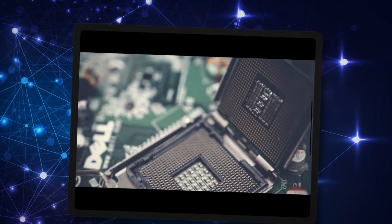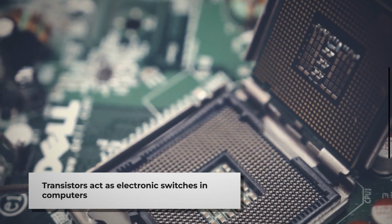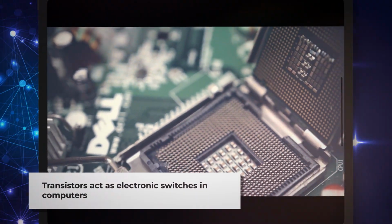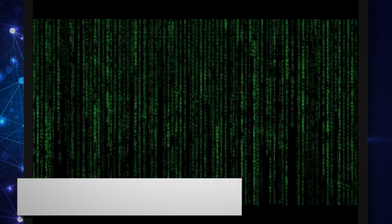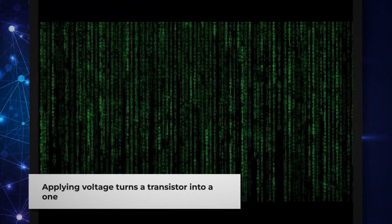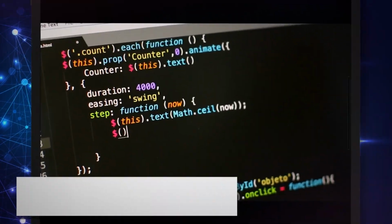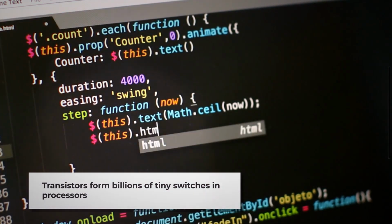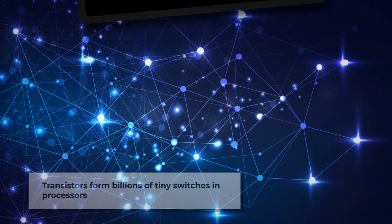The physical component that creates these ones and zeros is called a transistor. A transistor is an electronic switch that can be turned on or off by applying voltage to it. When a small voltage is applied to the control part of a transistor, it allows current to flow through, creating a 1. When no voltage is applied, no current flows, creating a 0. Modern processors contain billions of these transistors, each smaller than a virus.